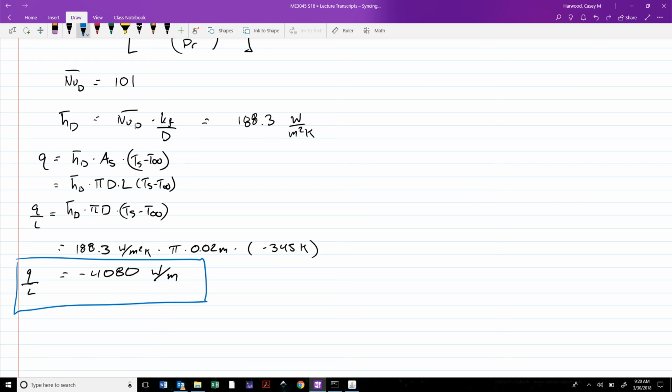You get to pick what kind of fins you want, whether it's circular pin fins or these flat plate style straight fins. And what you're going to need to do is use the correct correlations to find h bar for whatever that geometry is. Then you're going to use that h bar to plug into the fin equations from Chapter 3 to figure out the total heat rate those fins generate.